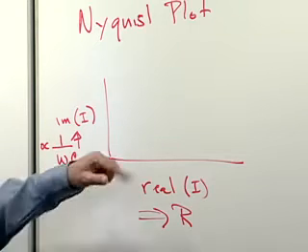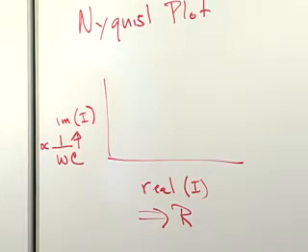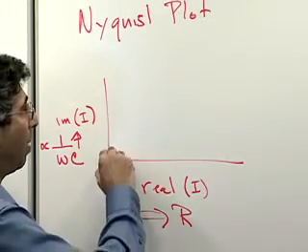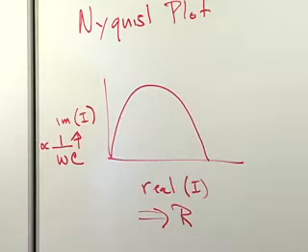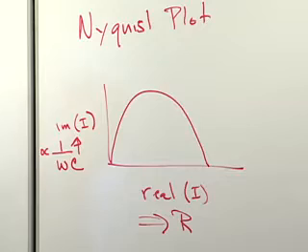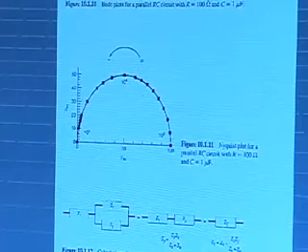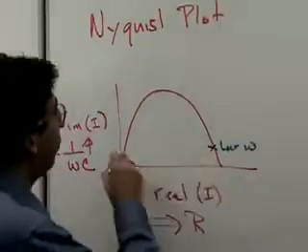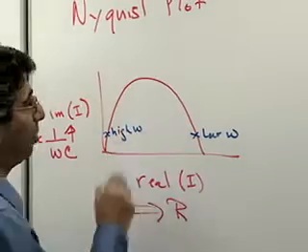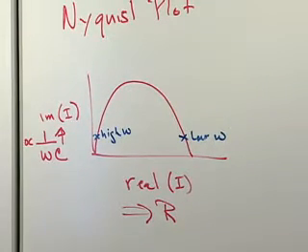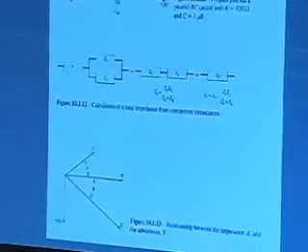Okay, and so if we have a pure RC circuit, nothing electrochemical, but a real live resistor and a capacitor in a circuit, then you'll get a plot just like shown on the PowerPoint. You get this nice semicircle here, where the total resistance of the circuit can be determined by where this circle or semicircle impinges on the resistive axis here. The way this is working is we're moving from low frequency to high frequency. We're generating that semicircle. Third way that, of course, you might try and analyze this is just in terms of the standard vector notation that one uses with the real and imaginary vectors.